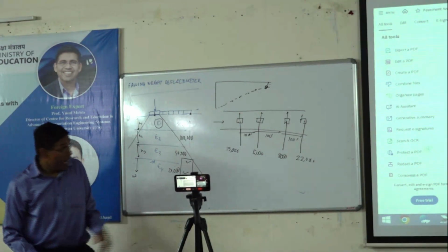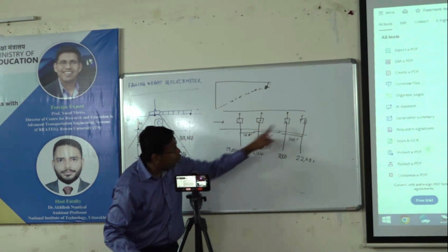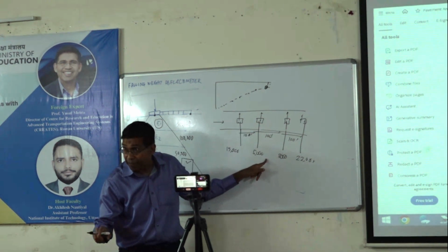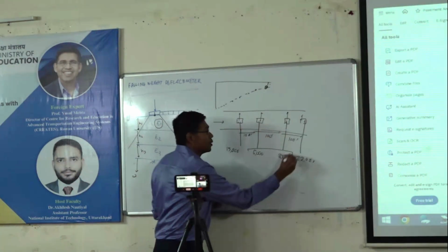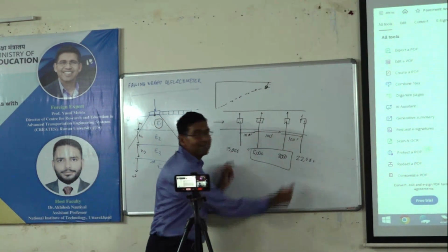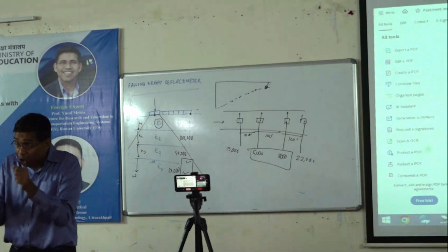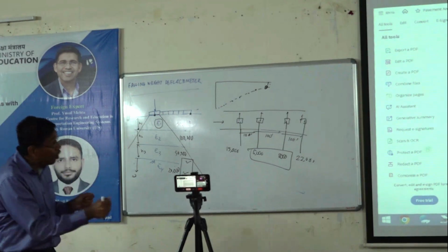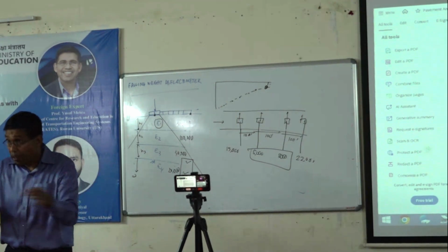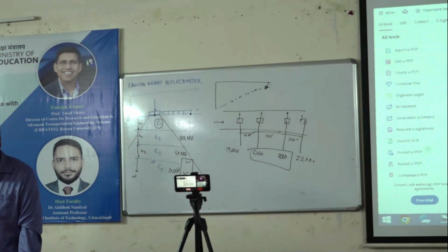Unless I have a very definite reason, something went wrong in the water at the subgrade level, these are bogus numbers. Or these are bogus numbers. Can everybody understand what I'm saying? Unless I have a logical reason to believe within 4 points the numbers drastically change, they should have been very close to each other. Everybody's with me so far.